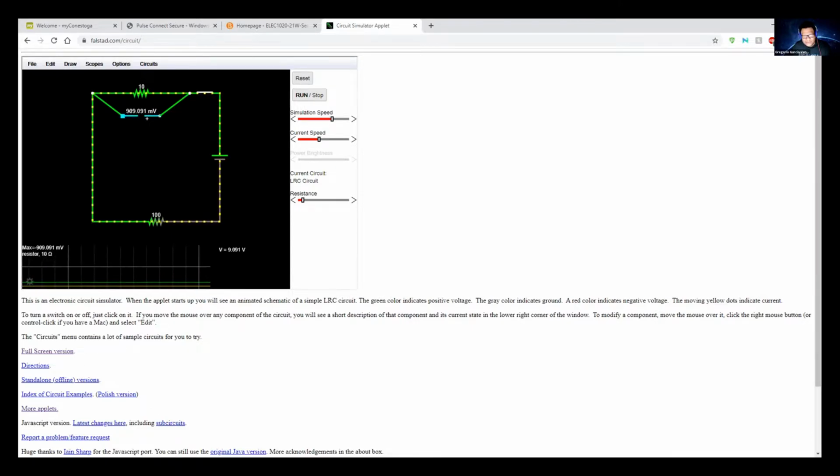When I do that, you can see that my voltage is now positive because my voltmeter is connected in the right polarity. If I want to measure the voltage down here, you can see it as well. Using my cursor, as soon as I go down to this other resistor, the connecting points are highlighted right away, okay? So I'm going to stop the simulation. Our connection points are highlighted here, the two squares at the bottom, right here and right here. So in this case I'm going to go back to my meter.